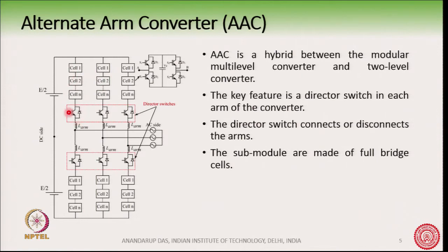With the help of this director switch, you can either connect this arm or disconnect it. Basically the converter is operated in such a way that only one arm is operating in one half cycle of the AC waveform.